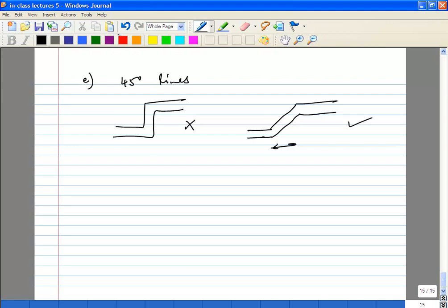Because typically when you are looking at high frequency currents, you tend to have current crowding. I think we looked at this when we saw the inductors, right? You'll end up having current crowding right at the turns, and so your density will increase. There are a lot of effects. There is something called electromigration, where if your current density increases at a particular point, your metal starts to erode. So you might have issues like that. So 45-degree turns are much better.